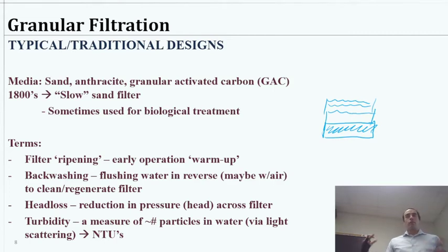And then if we have any disruption, then maybe it gets shaken a little bit and all sorts of particles start spilling out. So basically we have to just clean it routinely. Because it's such a simple physical process that's catching the particles, it turns out it's a pretty simple physical process to remove them, right? So the backwashing process is very nice in a sense that this whole thing is pretty simple and straightforward, and we can then continuously use this granular media so long as we have a good backwashing cycle.